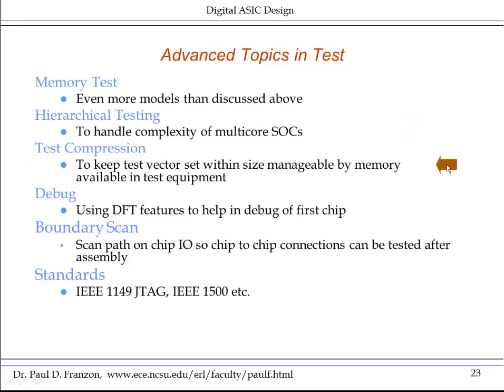Test compression. There have been a lot of advances in this area in the last few years. That is how to produce the minimal set of test vectors that maximizes the fault coverage. And there are often separate tools that run for this besides those embedded in synthesis.